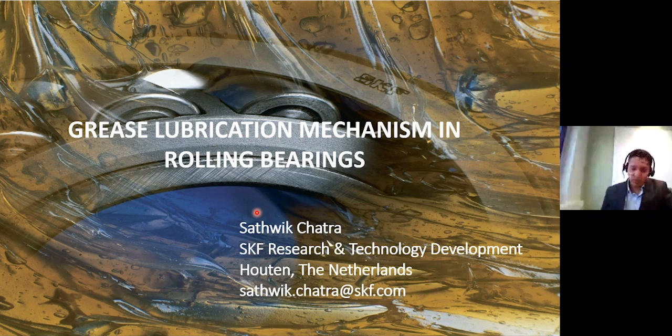The reason to do so is that we believe that the formation of a healthy film thickness and the deterioration of the film thickness has a direct impact on the bearing performance. That means when you have a very well developed film thickness, you're going to get a very good grease performance and thus good bearing performance too.